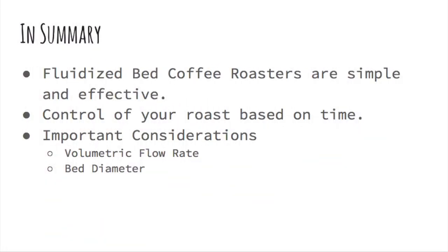So, in summary, we hope you take away from this video that fluidized bed coffee roasters are relatively simple to make. In addition to that, you can very much control the darkness of your roast based on how long you roast the coffee beans for. And finally, that if you do decide to build your own, some important considerations would be the volumetric flow rate of your heat gun as well as the bed diameter.